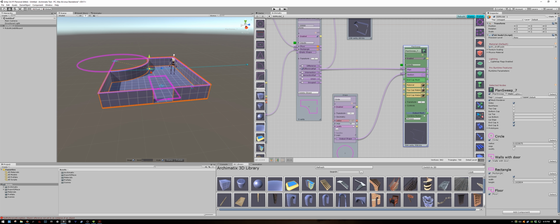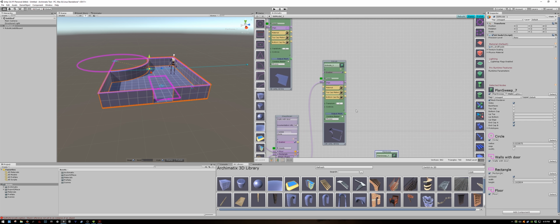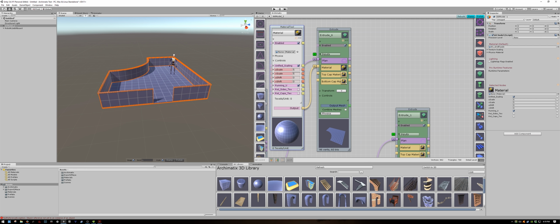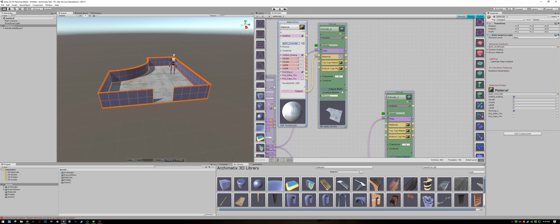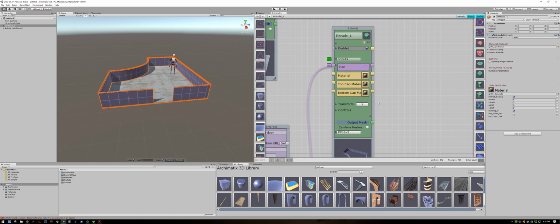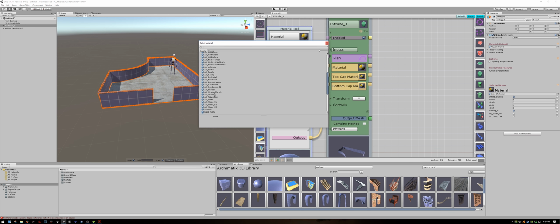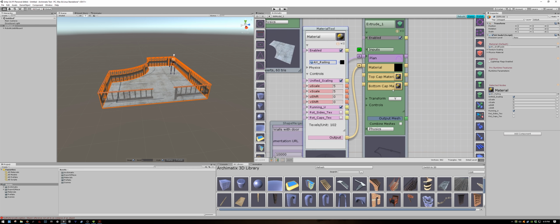As you can see, there are yellow material inputs in our green nodes. For the floor plan, I will click the material, and it creates a material tool that I can assign something. So clicking the dot next to the material, I can pick something, for example, I don't know, concrete. Let's go with concrete. The extrude node, which is our walls, also has a material. Let's give it a different material. For this one, I'm gonna pick a material that has a transparency, for example, the AX railing material. All of these are in the library of Archimatix.